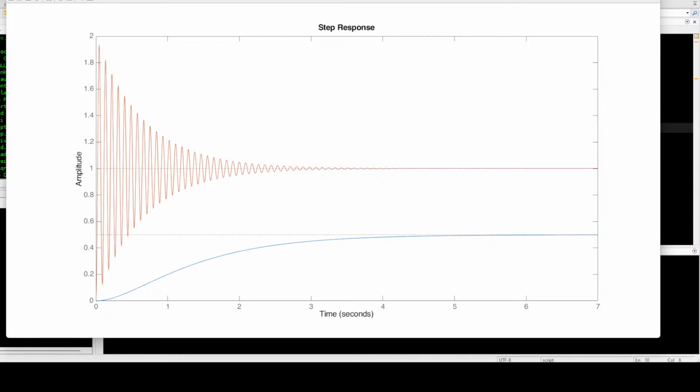It reaches the ultimate gain KU, where the output of the control loop has stable and consistent oscillations. I'm just reading something on the side here. KU and TU. Aggressive gain and overshoot, okay. Hang on, let's try a different way. Rules for tuning PIDs, the Pessen integral rule.